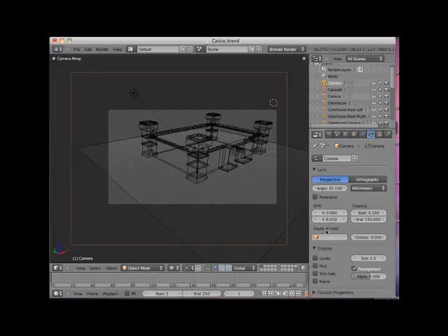The next area of camera control is called clipping. To demonstrate clipping, we need to first go to the Display Panel, just below the Lens panel, and checkmark Display Limits. This displays the extent of the camera's view. I'll also go to Quad View, Control-Alt-Q.